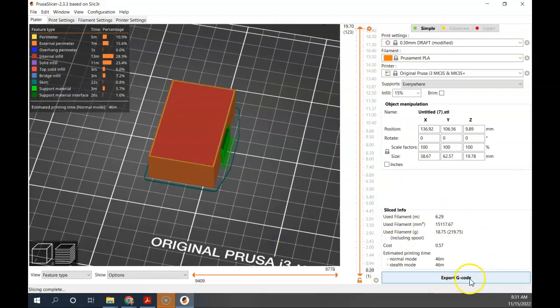When you're happy, you click this G code. This is a machining language that basically instructs the 3D printer where to move, how long to stay there, to heat up, to cool down, and is just direct instructions for how to move the machinery around. You probably never need to look at this, but you're going to need that file, and you're going to put it on a little SD card. So at this moment, you'd go grab the SD card from the 3D printer, get a little SD card reader from Mr. Laird, and plug it into your machine, and then you're going to hit Export G-code.